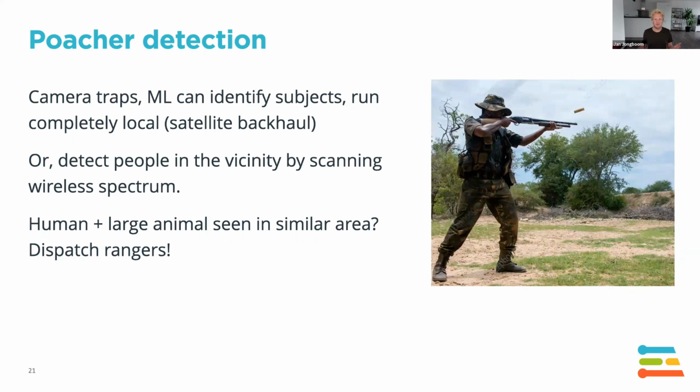What they can do now, and what Q42 is doing in their first iteration, and we're working with them on a second iteration of this camera product, is that they deploy this battery powered with a solar panel, communication back over either LoRa or 4G, like cellular, or over satellite backhaul, and then you send back whenever there's something around. And this is really cool because you do all of these calculations locally on the device, only when there's movement. This is actually feasible from a power perspective. It's a complete standalone product that basically doesn't need anything to happen anymore.